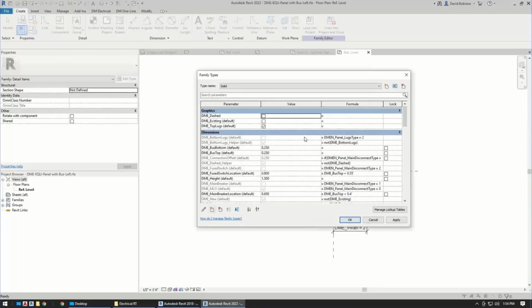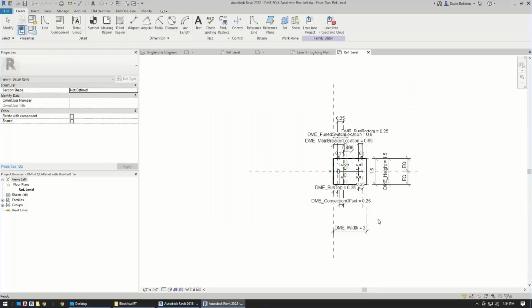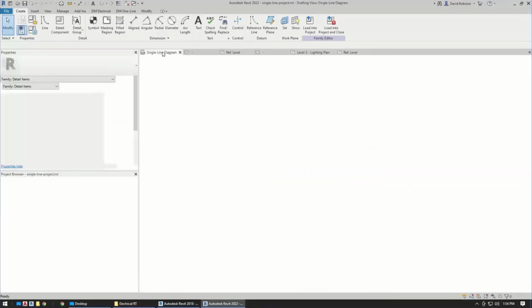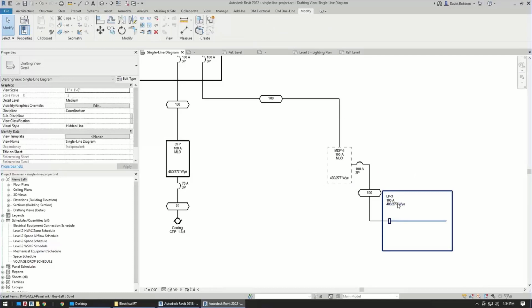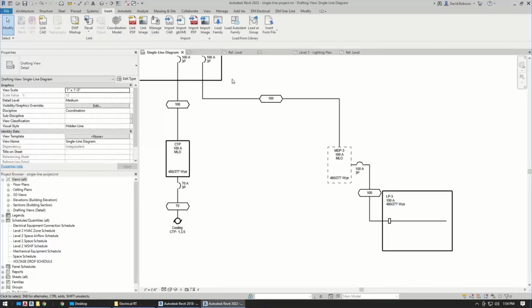So that's how you can add additional shared parameters to the families. And then you also use those shared parameters to create new annotation tags. So we include a number of annotation tags that are inserted by default. There are also a number that we ship that aren't otherwise used that you can load. And you load those, again, using standard Revit functionality.